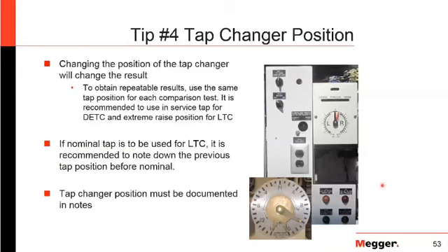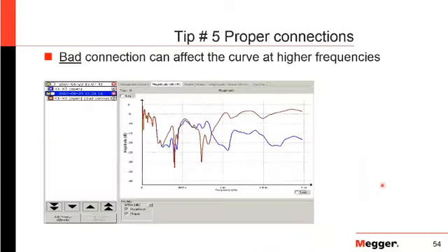Well, what it was is this was a bad connection, and this was taken at first with a typical alligator clip, like a jumper cable type clamp. So they went back and cleaned the connection, made sure it was a good connection, and now you can see, once again, these pretty much overlay each other. And this is why you want a nice, good connection, using a C-clamp, so that when you go down, it's connected, you're solid there. And from this, I've seen some people actually go through and measure the termination impedance